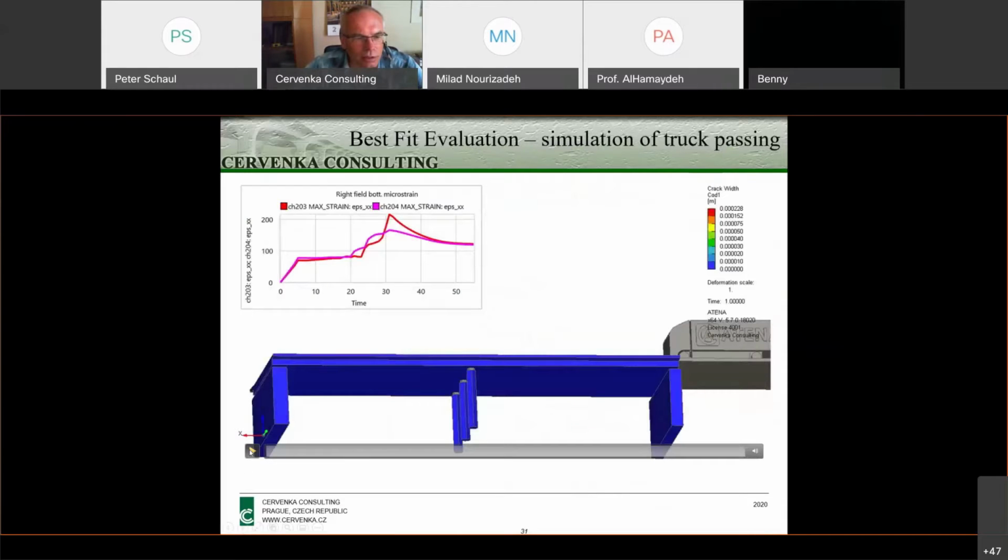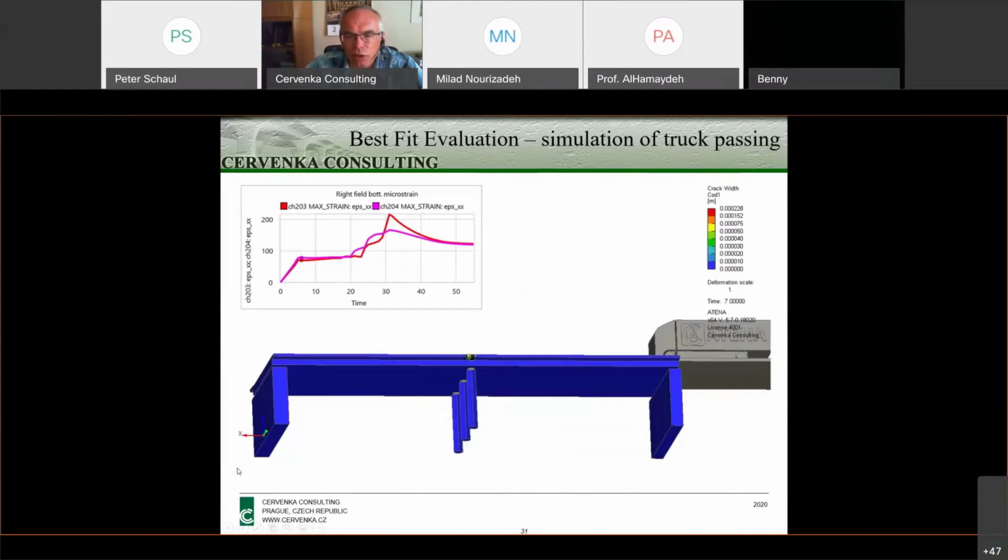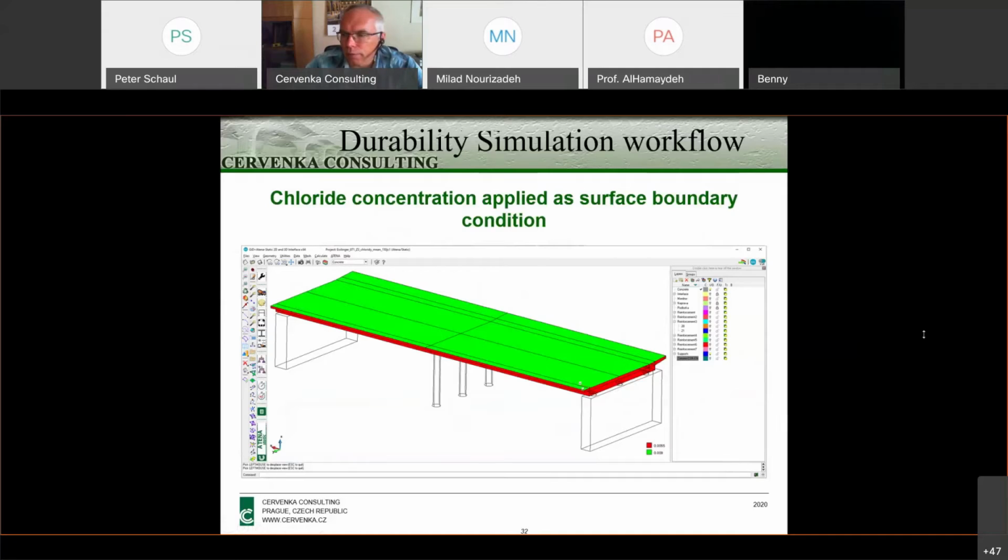And this can then show you the process of this calibration. We then were passing the trucks which were measured. And the advantage of this is that this system was introduced there for a longer time. And it recorded the weight of the various vehicles, and then we could use this calibration using the real traffic of the bridge. And then, after the model was calibrated, we could simulate also or make some live predictions.